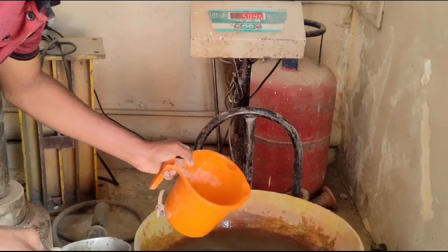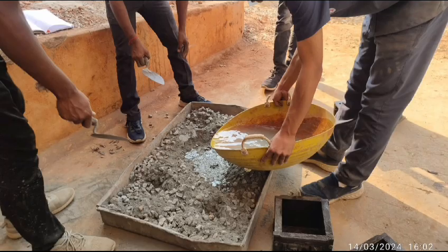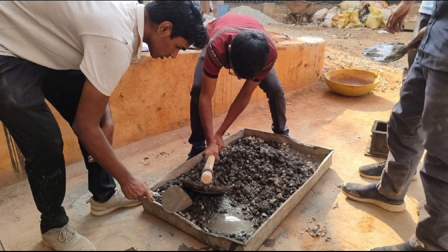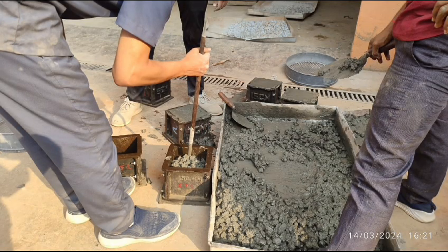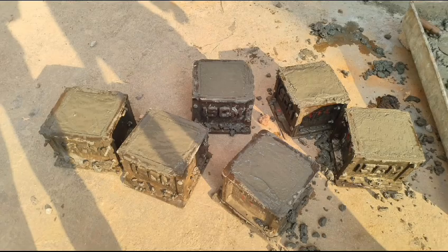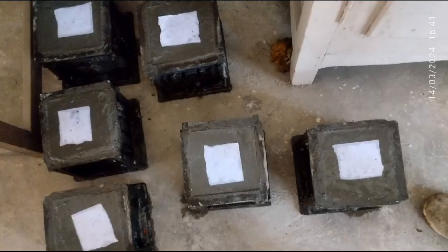To cast 6 cubes, we require 5.04 kg of water. Now start adding the water to the dry mix and obtain a uniform concrete. Fill the cube molds in 2 layers by giving 35 blows for each layer. After filling these molds, keep these molds in a moist condition for 24 hours and then put them in a